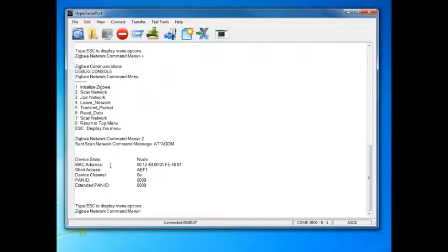Here you can add your own code to return information about what's going on inside the microcontroller code. Because the debug console is called once per cycle in the user app loop, it won't interfere with any of the functioning in your system.